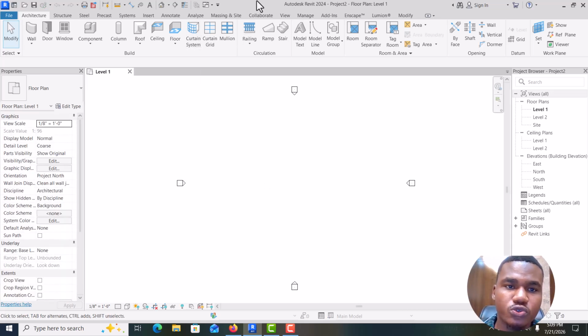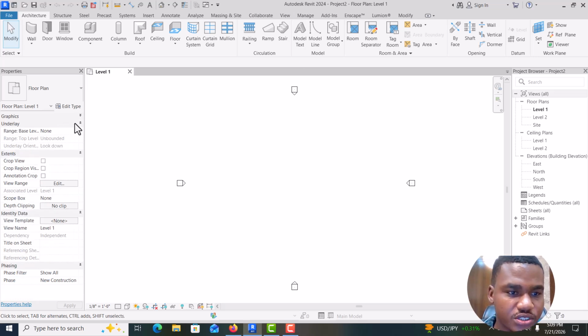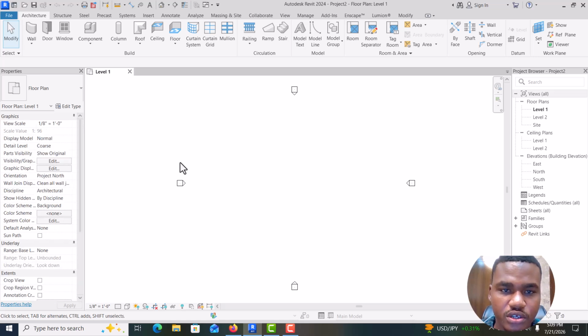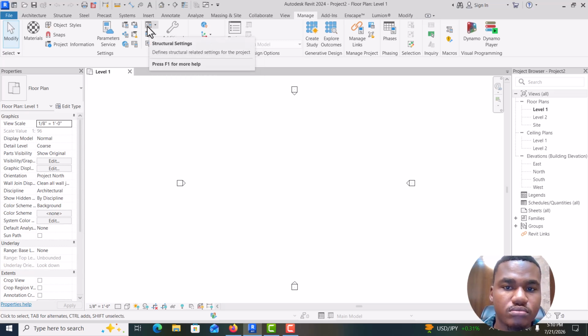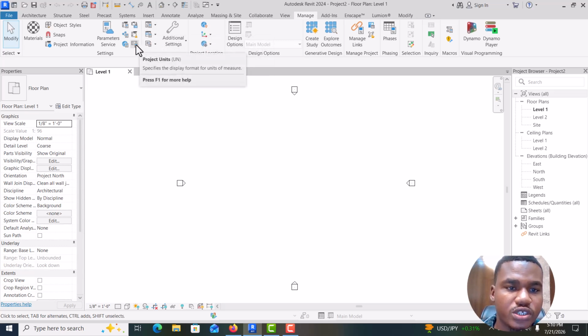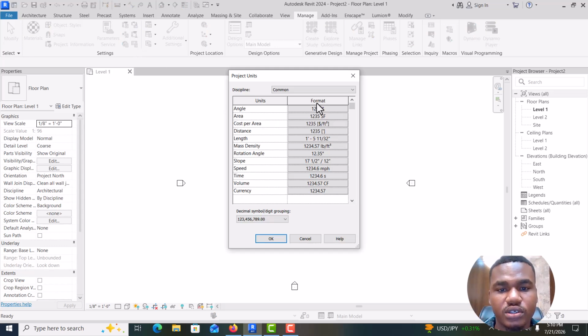First thing first, you want to go and change your units. You understand? Change your units because as you can see now, it's in inches. You don't want it in inches if you're in Nigeria, so you have to change your units. So you go to manage, then units, and come here. Project. Have you seen the project unit?